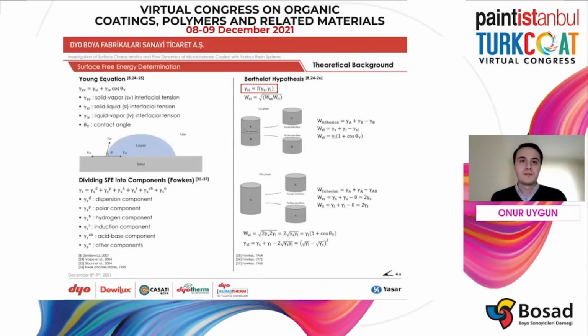So if you look at the theoretical background of this study, as most researchers in this field would know, we can say that the main or the fundamental part of surface free energy determination is contact angle measurement and the three-phase equilibrium equation of Young.